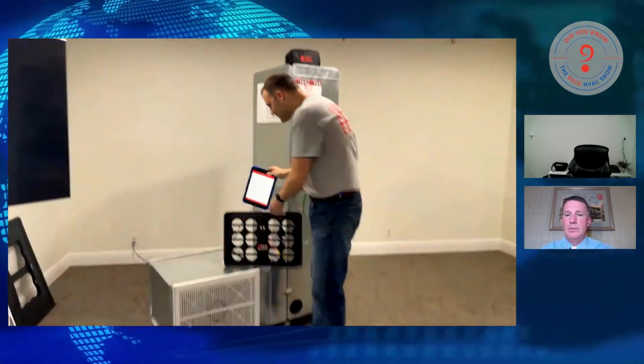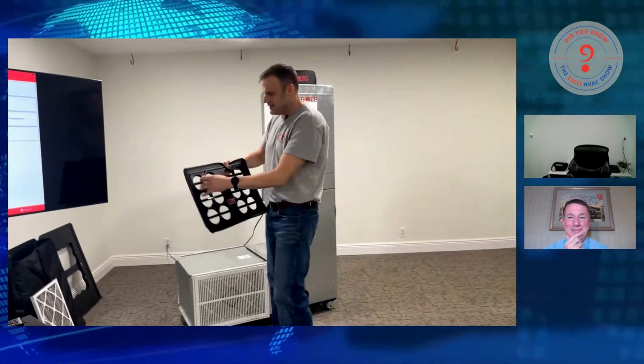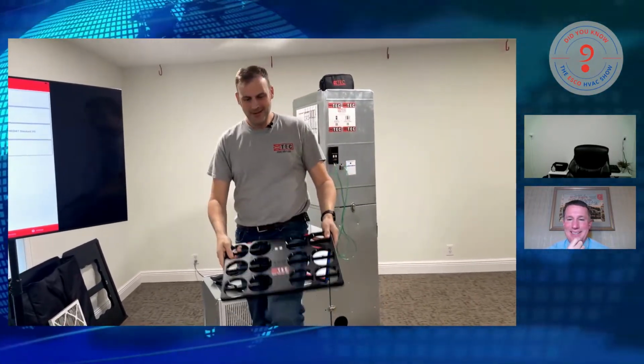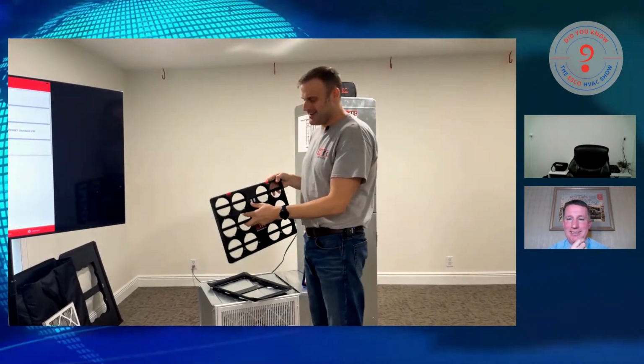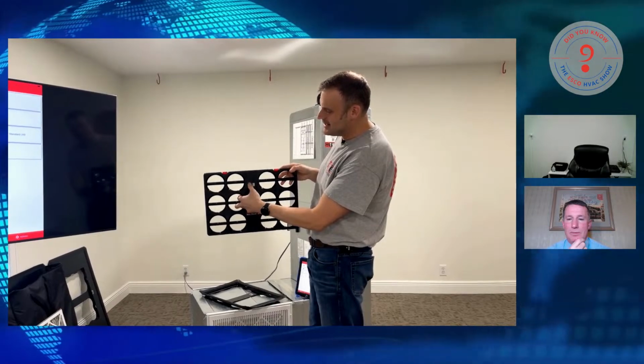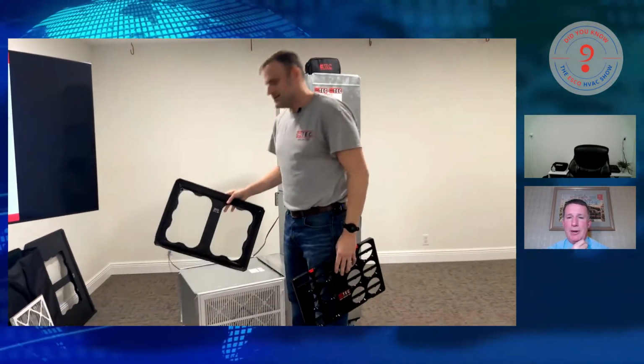Now, let's cover the tools. This is the digital Trueflow Grid. It's an airflow measurement device. It's heavy duty, you drop it, more than likely not going to break. It's got a power button on the left side. We're going to hold it down until it flashes and then let it go. Once we do that, it's powered up. It uses rechargeable batteries, and you'll get about 22 hours of use out of this thing if you ran it nonstop.